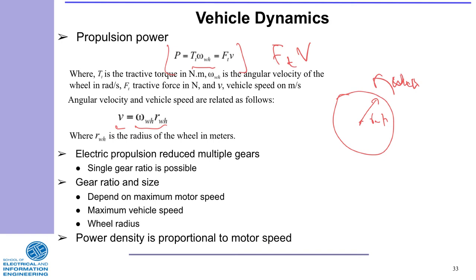All right, now let's go back to how we move. The question now is, how do we take the power at the wheel? We know what type of acceleration we want on the vehicle we are designing for. We also know what forces are acting on the vehicle, and now we know the tractive force that we need.